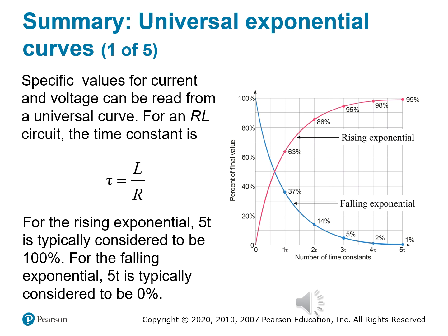For a falling exponential, such as the voltage across an inductor collapsing after a switch opens, you'll see again at 1 tau the voltage having dropped to 37%. Now realize that if we're rising, it's 63%. If we're dropping, it's 37%. A good way to remember these is that both of those have to add up to 100%, right? So 63 and 37 make 100. By 5 tau, it's down to just 1%. On the other side, it was up at 99%. So 99 and 1% should equal 100.